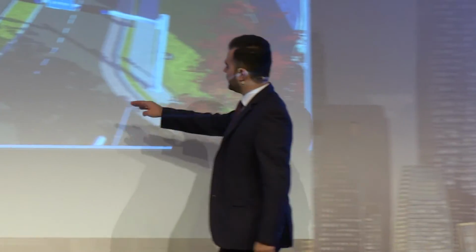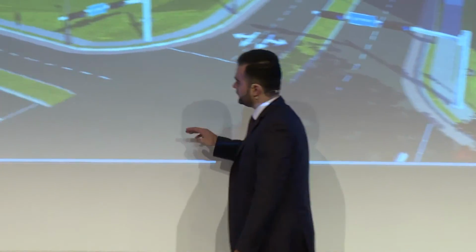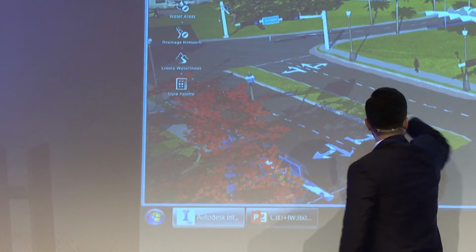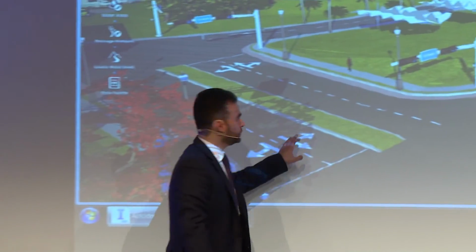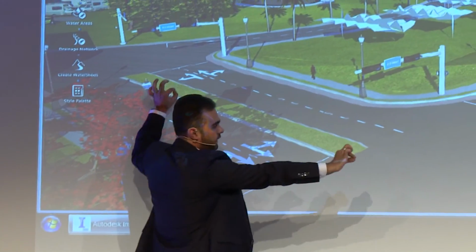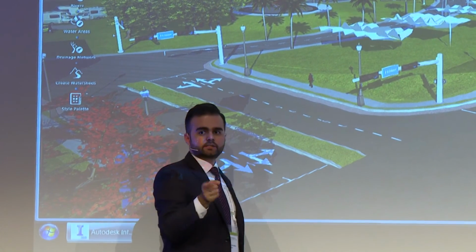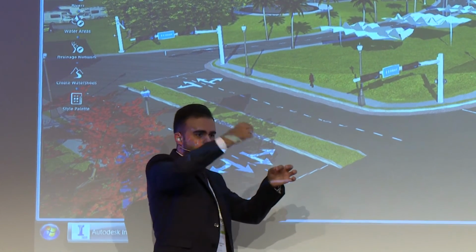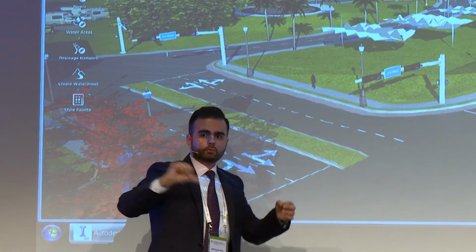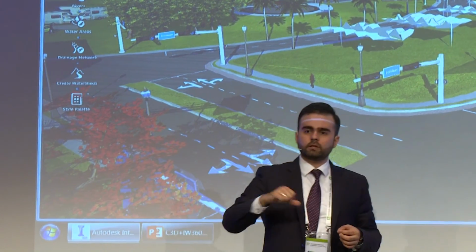So if, for example, I know that I want to sketch a road from this point to this point, and it's a straight one, the software knows I am specifying the alignment. I can ask it to optimize the profile. It will optimize the vertical profile for me to minimize the cut and fill and minimize the cost. But this one also requires cloud credits because it's done in the cloud and then pushed into your machine.